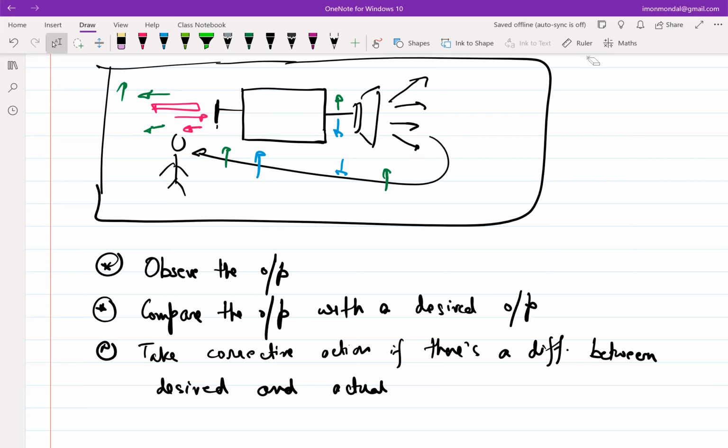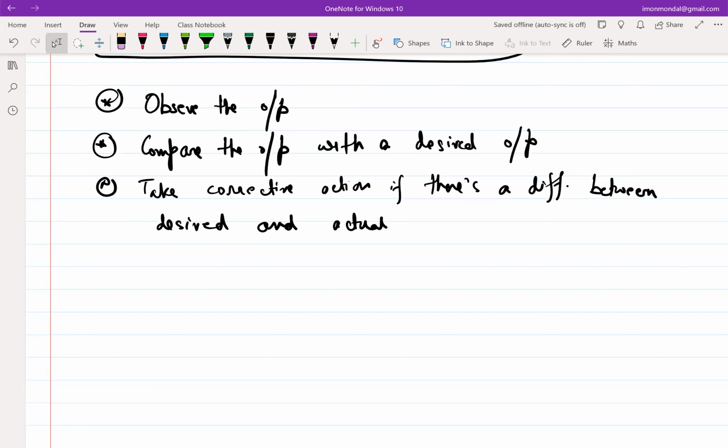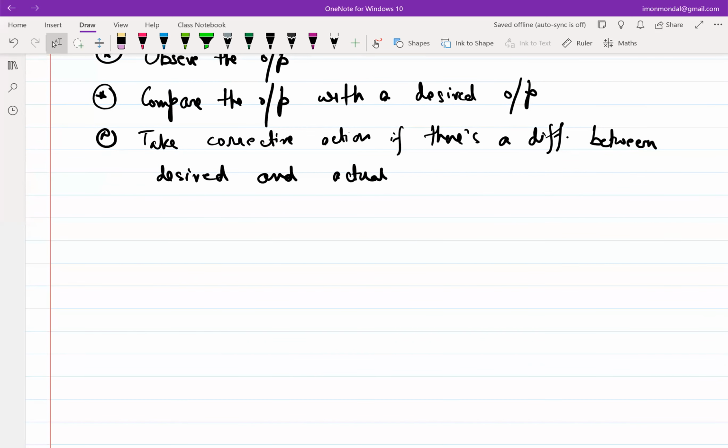So this type of negative feedback can give you stability in terms of the output. The output level that you want can be made invariant to temperature variation, invariant to ambient variation. That is why you seldom design systems without negative feedback, simply because you want the experience of using whatever network or circuit you are making to be reliable. So essentially, we would like to make an amplifier using negative feedback because of all these good things.